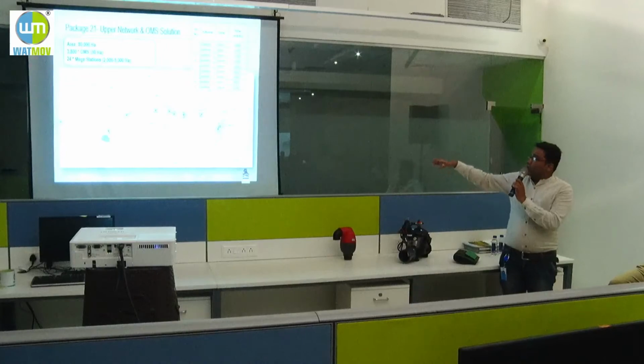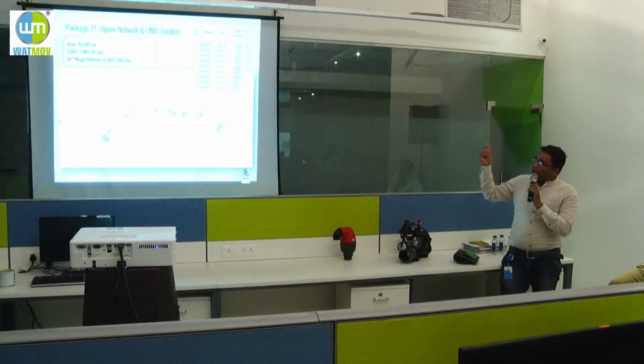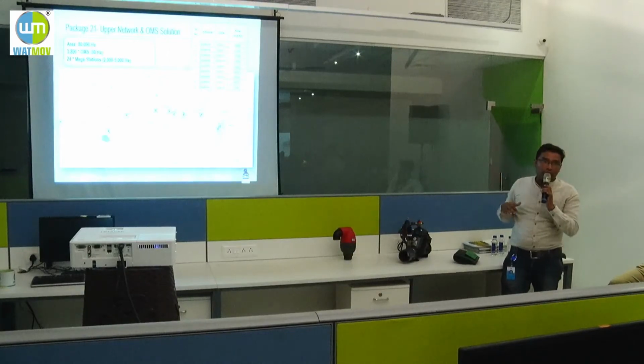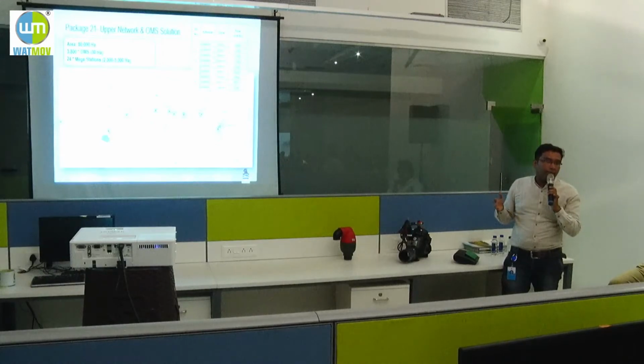Now, when we come to the practical condition, all outlets are not running at a time. This is the practical scenario. Even 10% of people may not be using water. The variation in the flow being utilized will drop drastically, but your pipelines are already designed for your full flow. And now if the entire flow is dropped, what happens? The pressure in your system will start increasing.